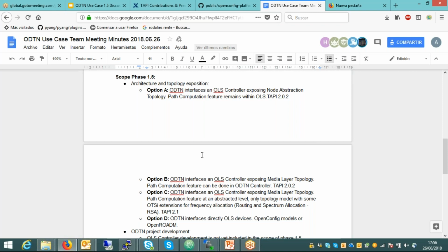So I think these are the limitations we should identify and state. We say, okay, we go for this architecture, but we are assuming some constraints, like those Gary mentioned before: you will have sequential service provisioning or path computation, because you will not be able to perform multiple path computations or service provisioning at once. You will also have limitations in the performance the equipment provides, because you will need to constrain the paths you set up for the media channels to a conservative range, in order to assure good quality of transmission for a given transmission format.